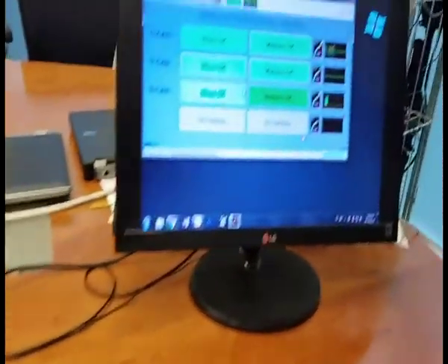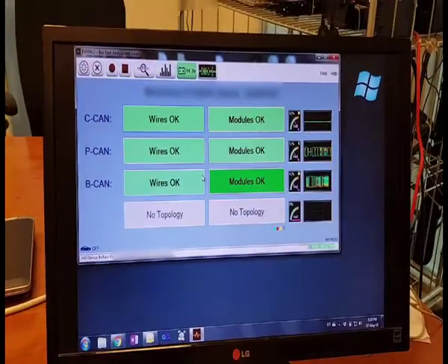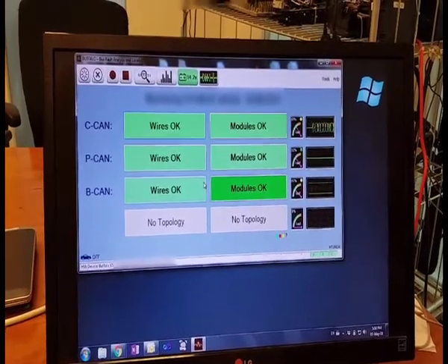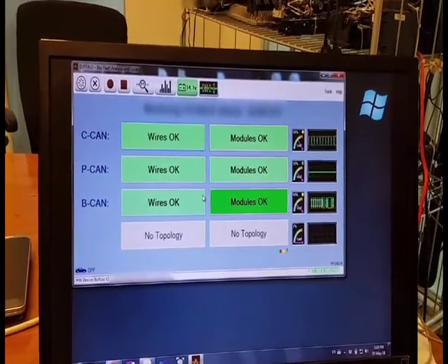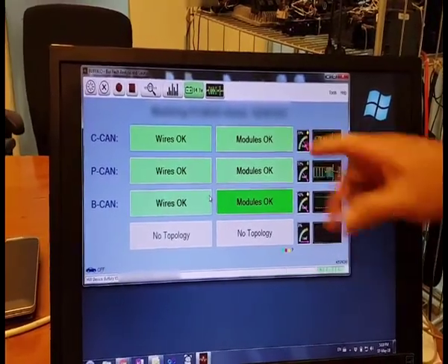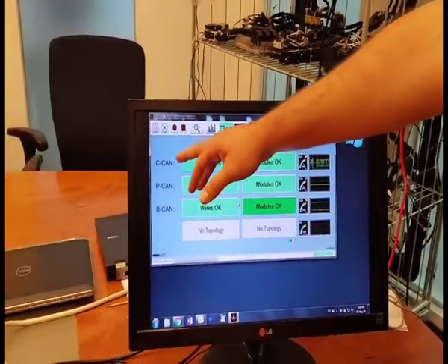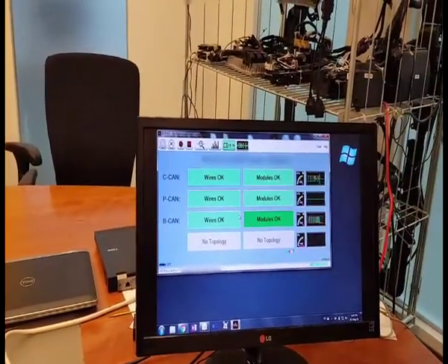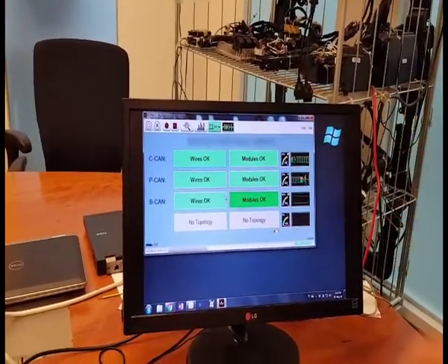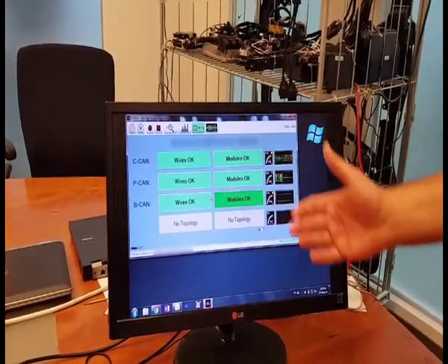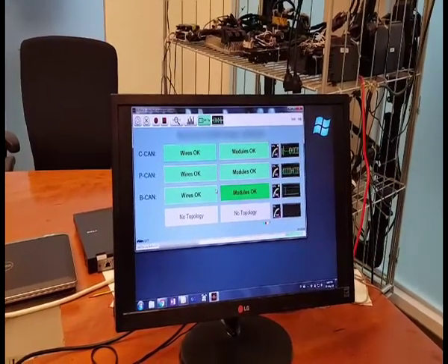for this demonstration. The Buffalo software in front of you provides you with various types of indicators in real time regarding the physical health conditions of the different CAN and CAN-FD networks. You can see that we monitor multiple CAN networks at the same time. We have an interface to the chassis network, the body CAN, as well as the powertrain. And we have colorful light indication for the different conditions of the bus.